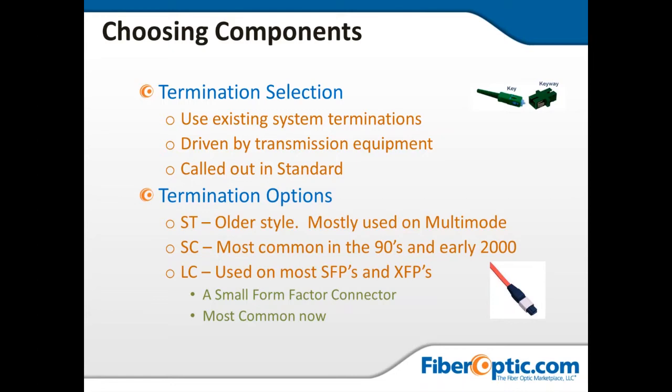We always want to get more and more into our fiber optic designs. What used to be a 48-port box, I want it to be a 96-port box without removing it, by replacing it. Now, shown in the picture is not an LC. You're going to see a multi-fiber push-on, or an MPO. And these little MPOs are kind of the footprint of a copper RJ jack, and can carry anywhere from 2, certainly past 12 or more fibers in the nose of the MPO shown there.